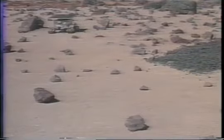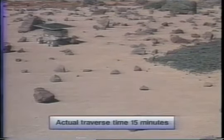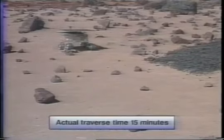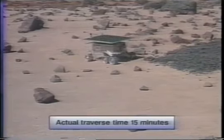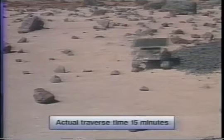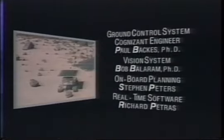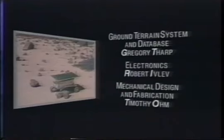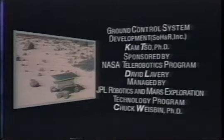The rover executes a long traverse at the end of the command sequence. During the traverse, it performs obstacle avoidance every 25 centimeters and uses its sun sensor for heading estimation. In the coming year, technologies will be developed to enable the rover to perform long-range missions independent of the lander. Extensive field tests covering multiple kilometers will demonstrate the integrated rover capabilities.